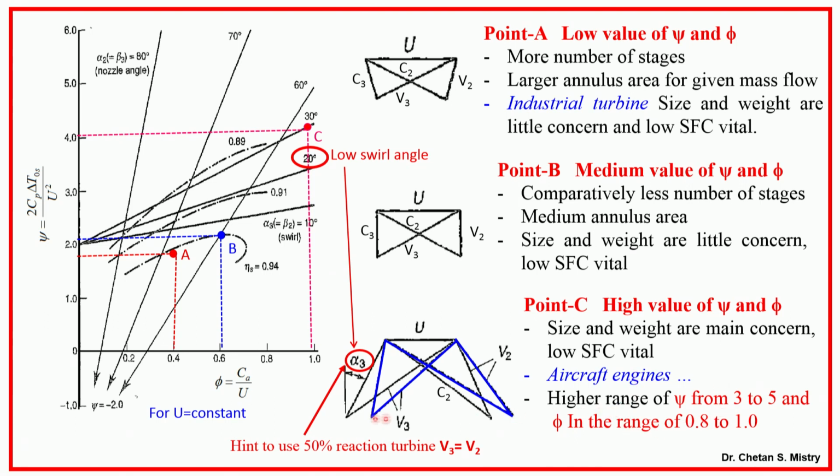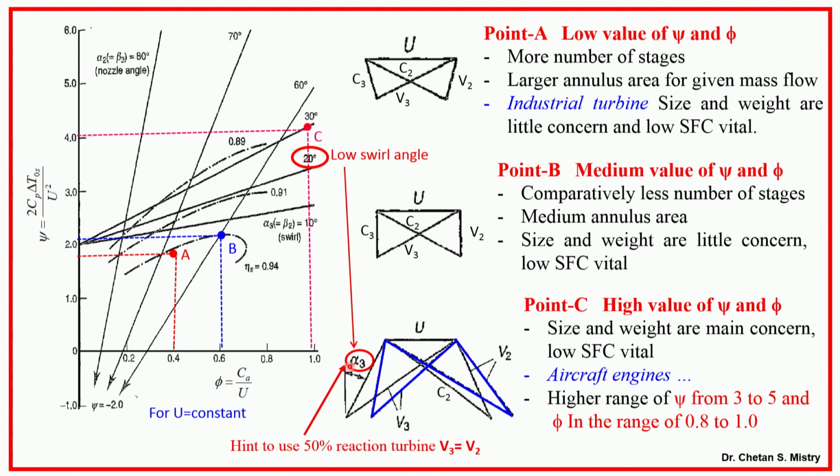Okay. Now, here if you look at, this is my velocity triangle. Now, for aircraft engine, suppose I am talking about the later stages, say LP turbine, my flow will be coming out at a certain angle, say alpha 3, that is nothing but my flow angularity. Now, that angular flow when it is entering downstream, say in the tail or nozzle, is subjected to loss.